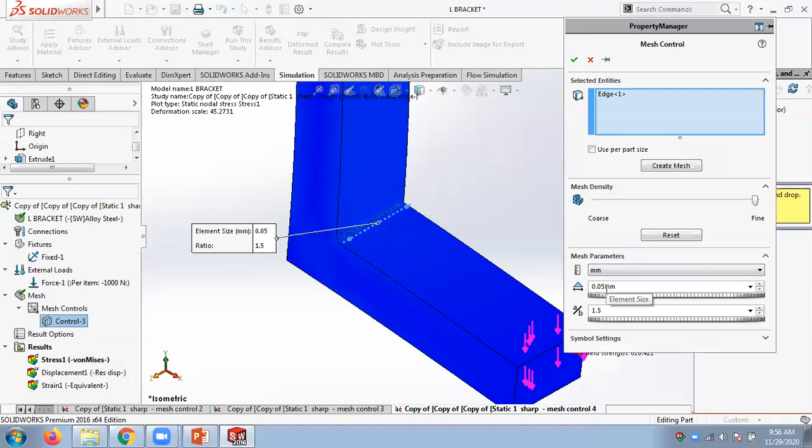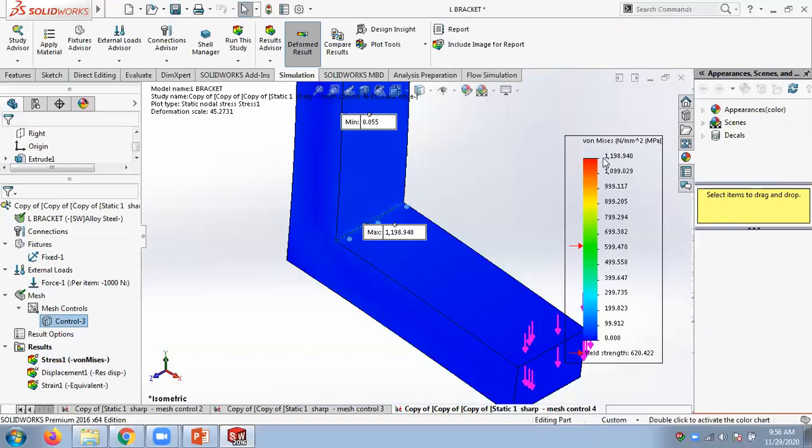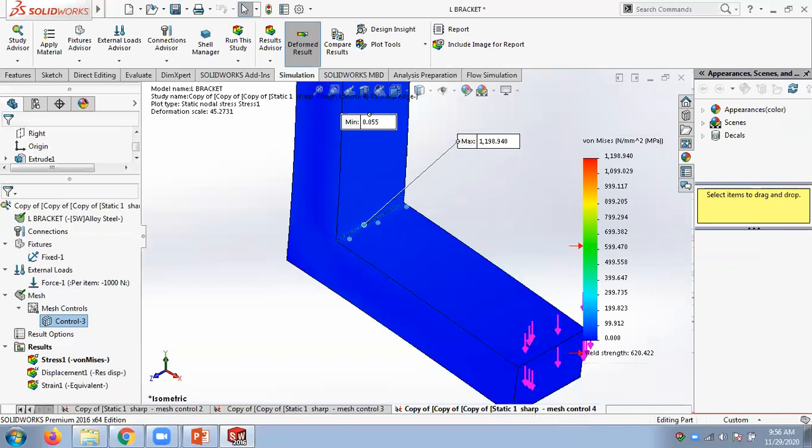So if I go to 0.01 mesh, my results will be obviously higher than this one. Theoretically it says infinite. Here as a numerical value we are getting very high megapascal values. So the theory is actually correct. We get big numbers here. So if I have a very good computer, I can have very fine measures and prove the theory from the computer simulations. So I hope you understood what I'm trying to say.